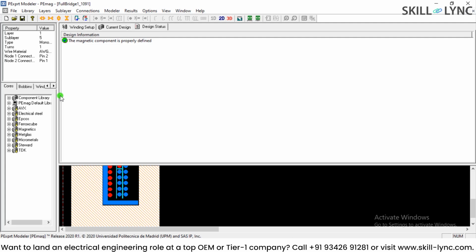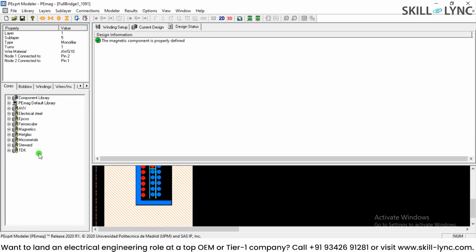So we created a full bridge DC-DC converter, and we analyzed how the Ansys tool will select the components from the available library and how it is suggesting us. What if you do not have any readily available component or any off the shelf component? Well, that is the case with most of the power converter. So the resistor, capacitors and other components like diode and switches, they are available off the shelf, or we just have to choose them. But when it comes to magnetics, you have to design them. So the power converter engineers will have the magnetic design exercise using inductor design and the transformer design, and this tool is going to be very effective for new design of a transformer or an inductor for a power converter. So these are the templates, and over here you can create your own component of transformer or inductor as well.